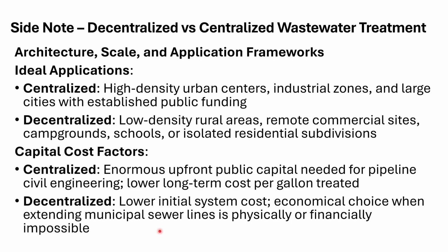Okay. Decentralized system, not a whole lot of upfront costs. You could get somebody with a backhoe and trench some pipe, PVC pipe, lay down some bedding sand, and then compact over that. You can put in some really quick, inexpensive fiberglass manholes, put a collar around them, put a cap on them, you're good to go. This is something you're going to see again in the rural areas.